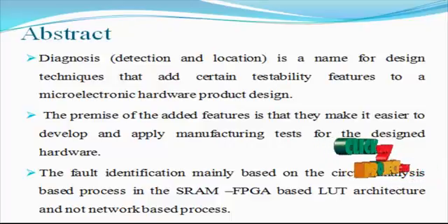This paper presents a new methodology for diagnosis, that is, detection and location of multiple faults in an application dependent interconnect of SRAM based FPGAs. For fault detection, the proposed technique retains the original interconnection configuration and modifies the function of the LUT using new LUT programming functions. These LUT programming functions consist of the 1-bit sum function. In addition, it utilizes features such as the branches in the net as well as the primary inputs and outputs of the FPGAs.